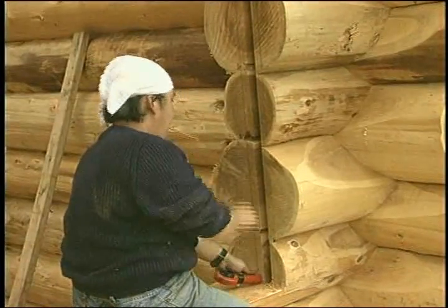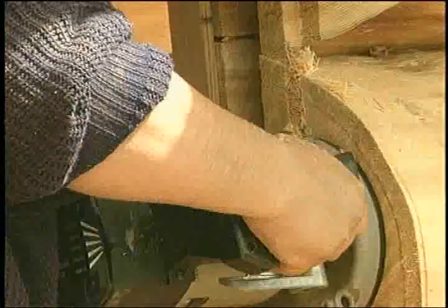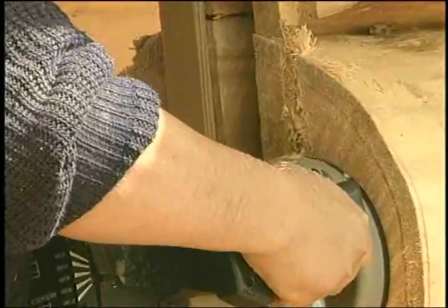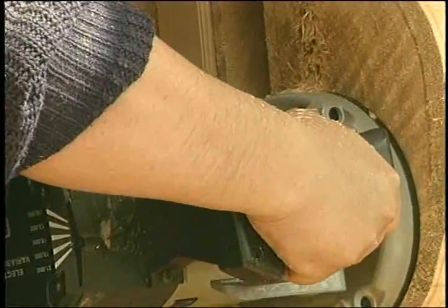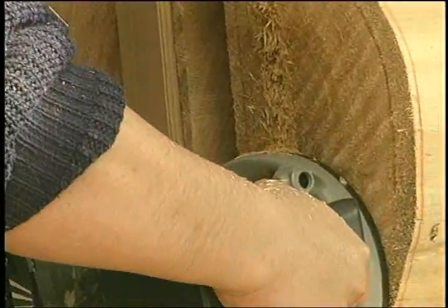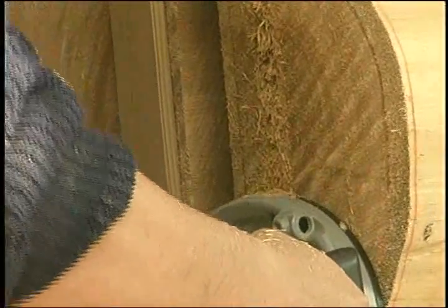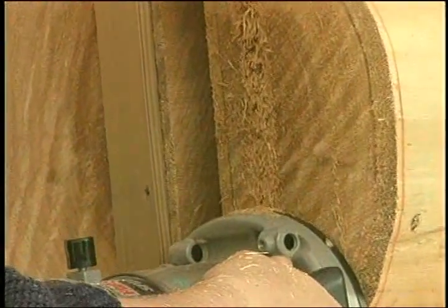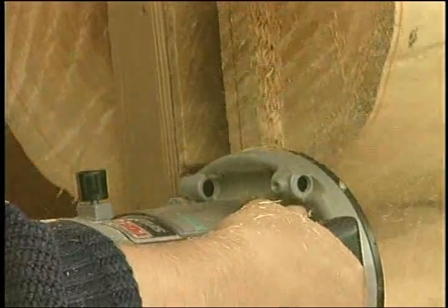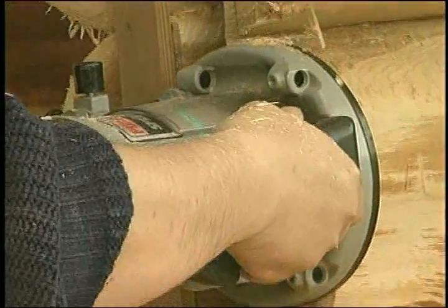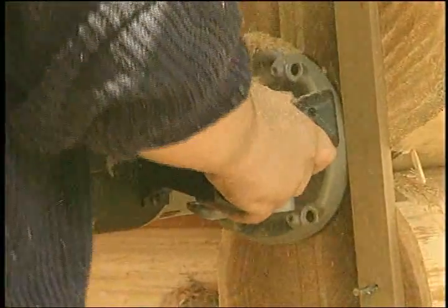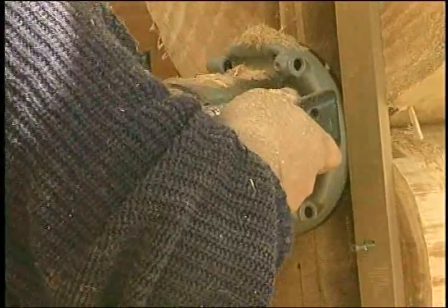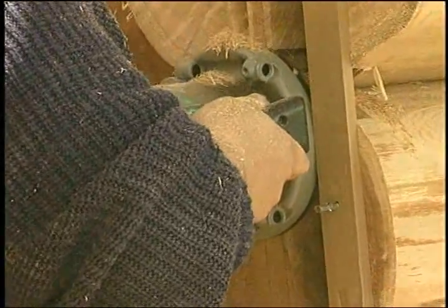Position a guide board and use a large router to cut the trim recess. If you don't have such a machine, make the bevel cuts on the log ends, then cut this step with a large chisel. The angle for the bevel can be marked on the bottom flat and the saw aligned with that. The angle of 45 degrees or less appeals to me, but many other design cuts are possible.